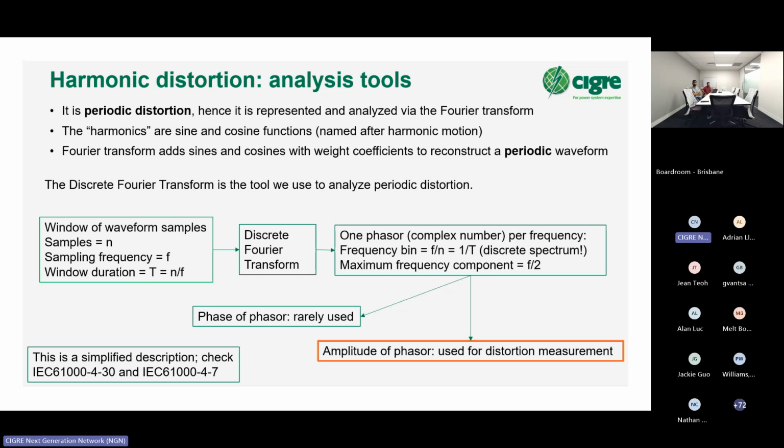Then we decide that we do a DFT on that, and we get an equal number of points, of which half are positive frequencies, half negative frequencies, according to how we set it up. Or it can be mirrored at the maximum frequency. What is the maximum frequency you can represent? Half the sampling frequency in conditions where there is zero noise.